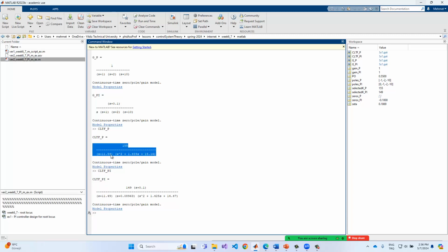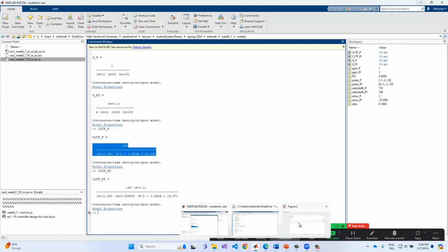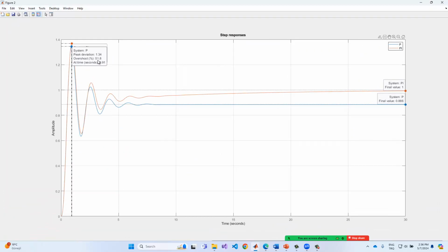And so the third order can be close to the response of these terms. Just see that 50 overshoot, we may reach it, but in the fourth order we have a different overshoot ratio. The difference is greater than the previous one. Bilge, see that? Just remember that this is important. If you want to design a higher order system, you cannot easily select the overshoot, steady state error, or the settling time parameters. But if we are using the integral controller, we don't have any steady state error at the final time, right?